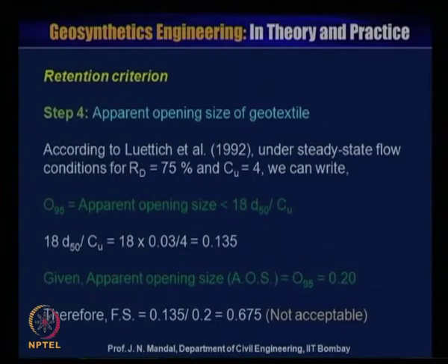Now, you have to check the retention criteria. That means step 5, you have to calculate what will be the apparent opening size of the geotextile material, or O95.